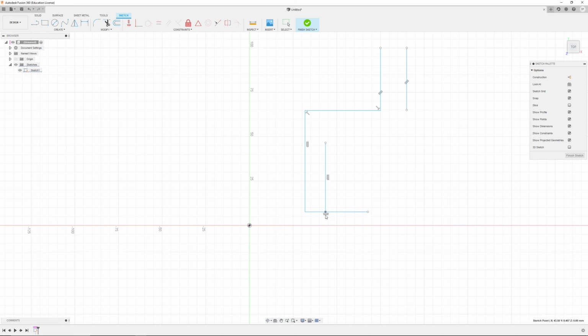no matter where that goes. If I make the points coincident, like so, if I can, let's see if I can add it. There it goes. You can see there it's got two coincident constraints now. That means that where that point is, those 2 points will always be in the same spot. Okay, I can do the same thing over here. So I can drag this and this point, make those coincident, just like that.